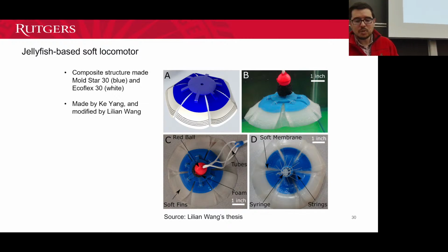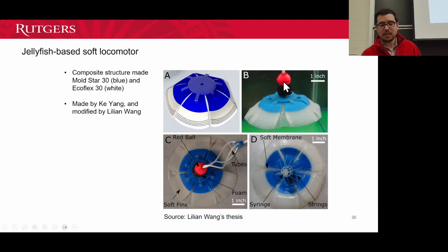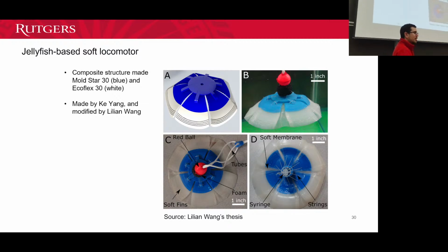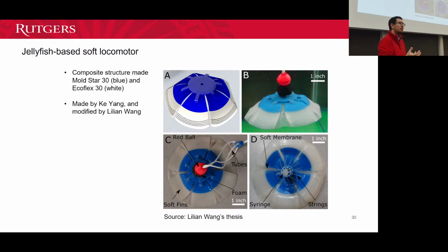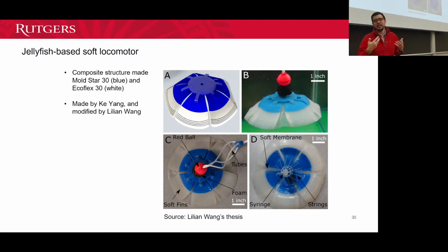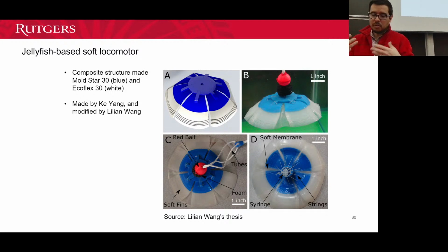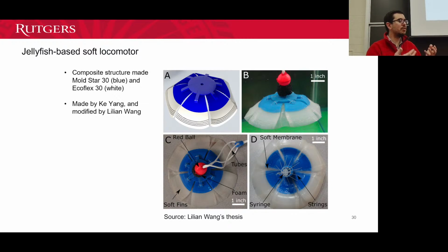This is a new jellyfish that has a clown nose on it. That clown nose is to get us to neutral buoyancy, because we were concerned about having the jellyfish move up and down instead of just horizontally. The people who do robotic jellyfish typically work this way. Like the work from Priya and Villanueva, they were also having their jellyfish with the shape memory alloys moving vertically.